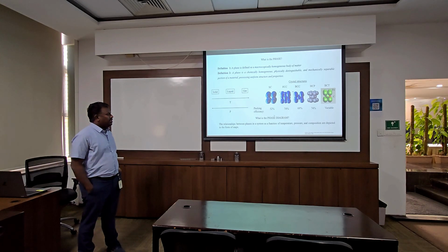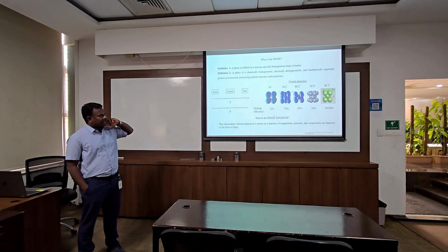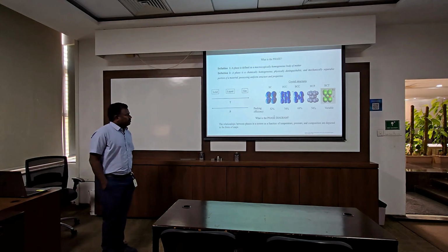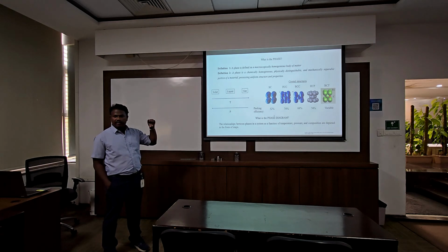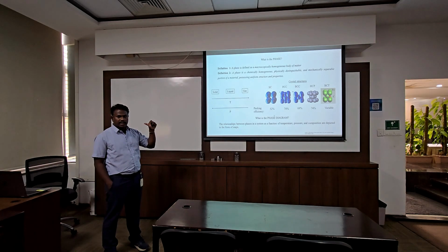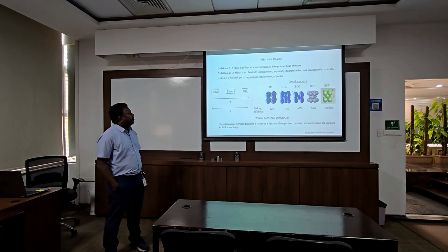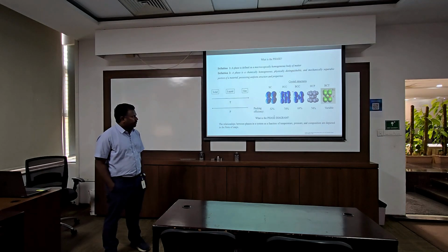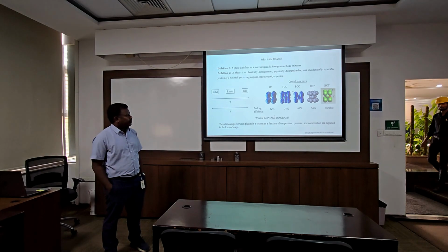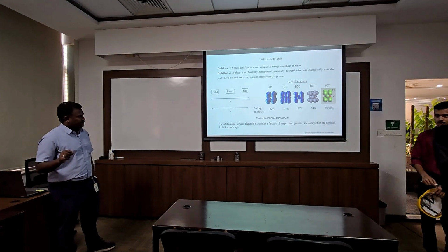Even within the solid itself, we know that a lot of crystal structures are there. Only five are depicted here, but there are many. If you see the packing efficiency, that means how densely we can pack the atoms within a crystal structure: simple cubic 52, followed by FCC 74, HCP 72, BCC 68. Ignore BCT because it is variable depending on the carbon concentration.